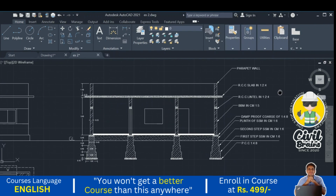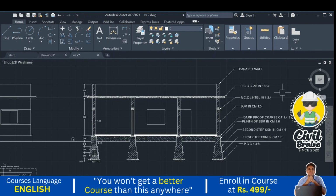Parapet wall. Okay, so here you can see this is a complete cross section of the particular building, correct? So in the presenting drawing, we need to show this complete cross section. We have shown the ground level, and below the ground level, whatever structures come, we have shown that also. Above the ground level, the plinth will come. Above the plinth, DPC comes.